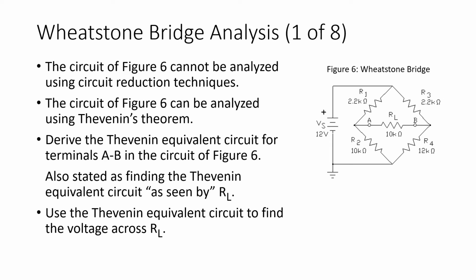However, we can use Thevenin's theorem to analyze this circuit. So what we're going to do is derive the Thevenin equivalent circuit for the terminals A and B in the circuit of figure 6. Again, we also state this as finding the Thevenin equivalent circuit as seen by RL. And then we're going to use the Thevenin equivalent circuit to find the voltage across RL.